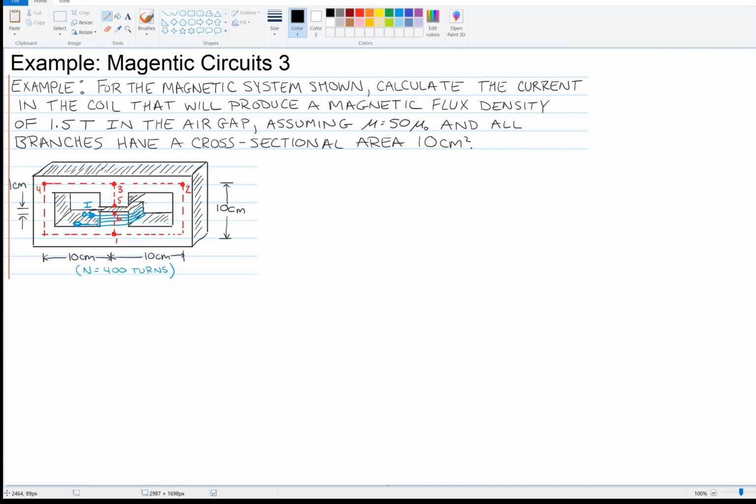And the idea is that in ferromagnetic materials, the BH relationship is not linear. It looks something like this, where this is B and this is H, and so mu actually changes. So what they're telling you here is that at this particular operating point, maybe we're operating here, the slope of the tangent is 50 mu 0. And in linear, non-ferromagnetic materials, this is just a line, and so that's why we never really talked about a BH curve before ferromagnetic materials.